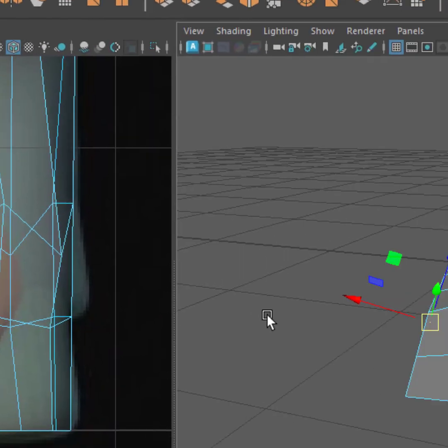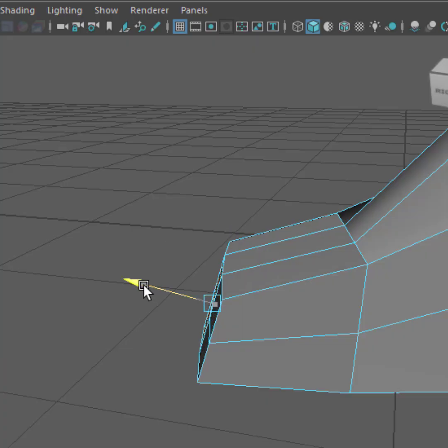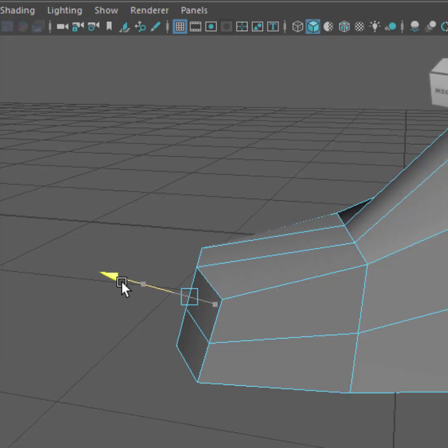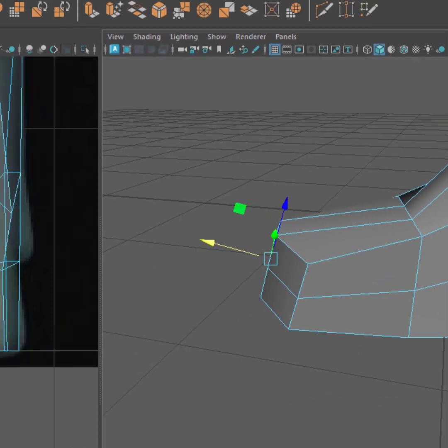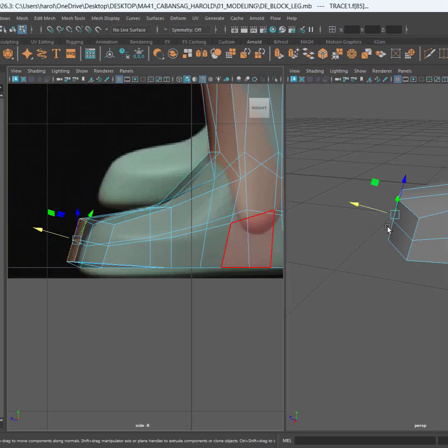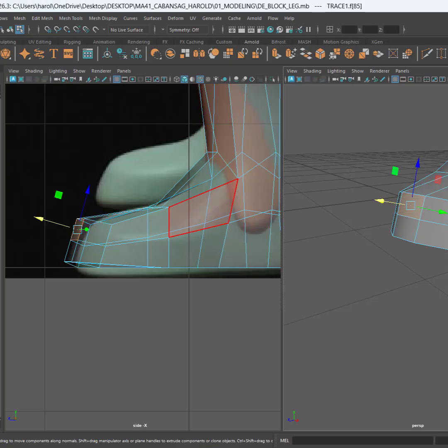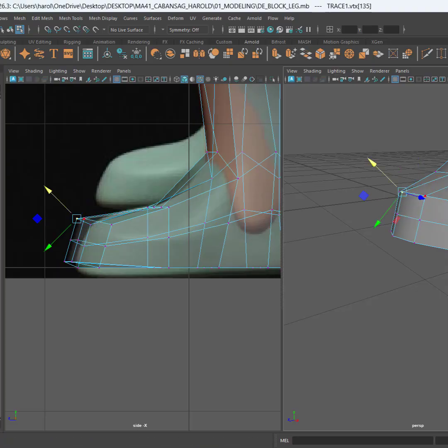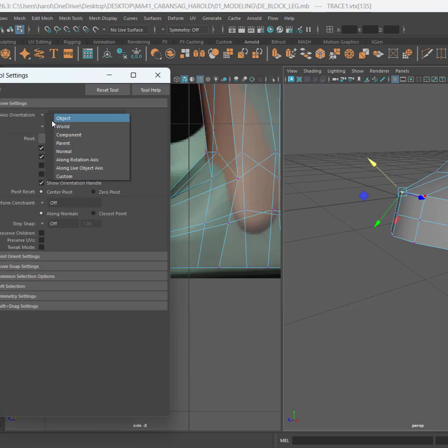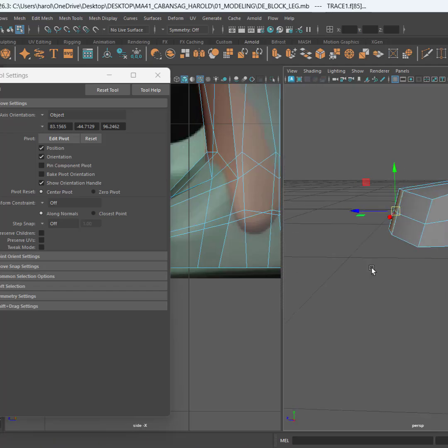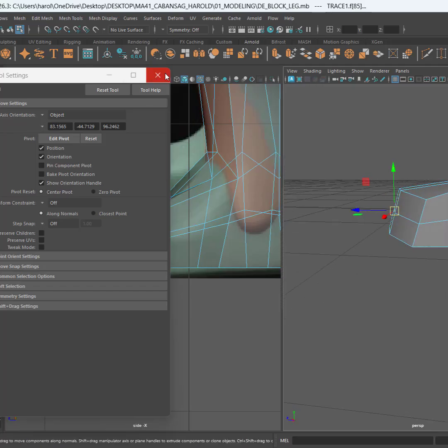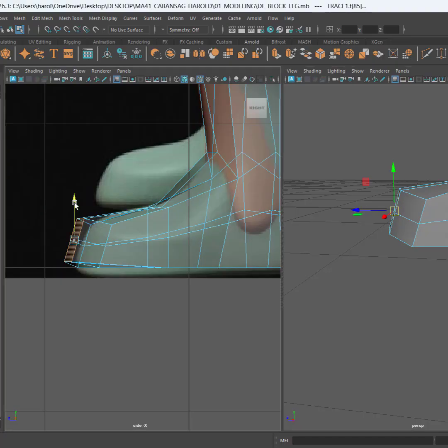They're slightly heading towards that, right? So I can drag it to that direction a little bit there, and then slightly I will now start to drag it down. So I can go to vertices, turn the component to object once more, go to polygon there, and then I will just drag down.